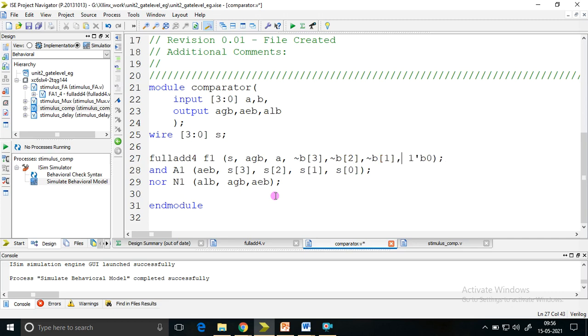That's why it is just acting as an adder. But the logic is that you need to understand where you went wrong. Here A is 4 bit, you already know A is 4 bit. B is also 4 bit, but it is down to 0. So that's why I took individual inputs B3, B2, B1, B0, and complemented everything.